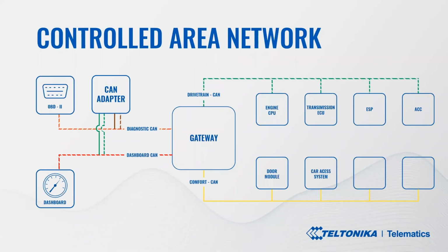All control units on the bus are effectively in parallel. That's why all of the nodes see all of the data all of the time. As a result of this logic, we can monitor the signal by directly connecting with our CAN solutions. Depending on the vehicle model, it is necessary to connect CAN 1 line or both CAN 1 and CAN 2 lines, since this grants us full access to listen to the transmitted data of main parameters.